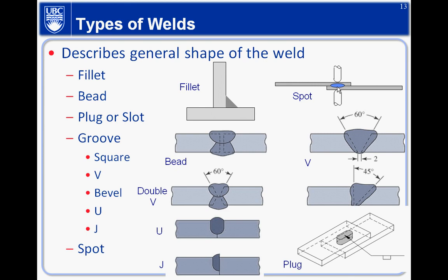Basically they use electrodes on two sides of the metal, causing an arc to pass through the metal, joining the two pieces of metal together. They might be sheet metal or something else. If you're moving along the metal instead of a spot, it's going to be a so-called seam weld. It's kind of like sealing the gap together. So that's spot weld.